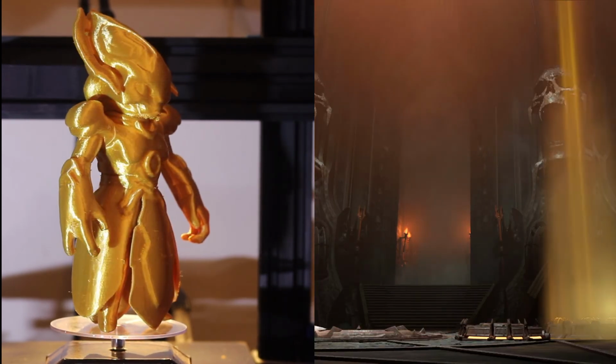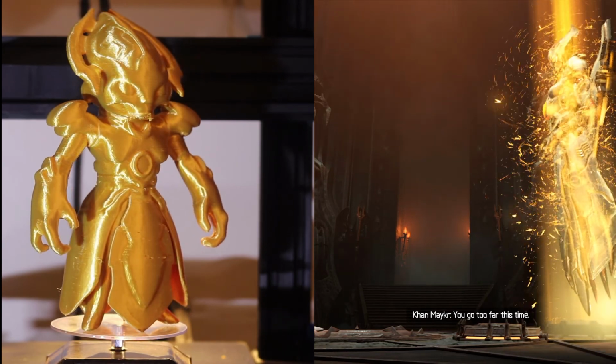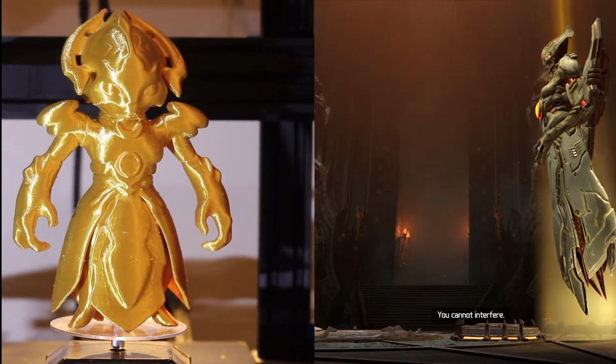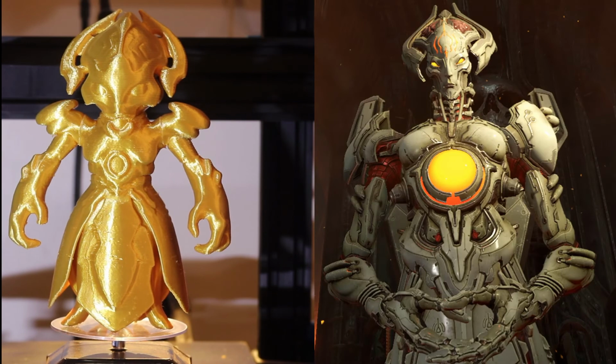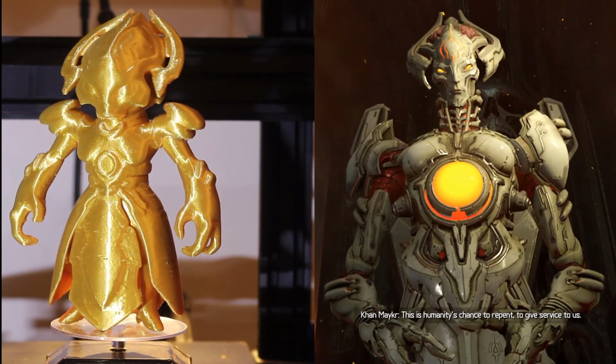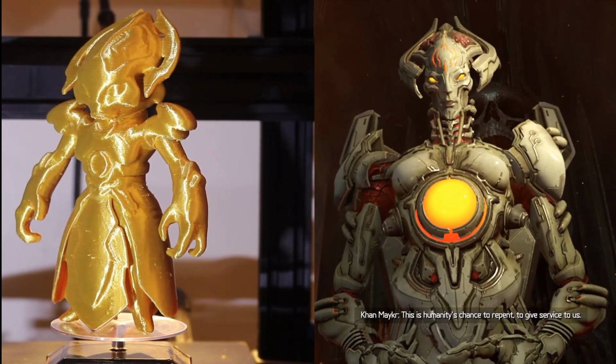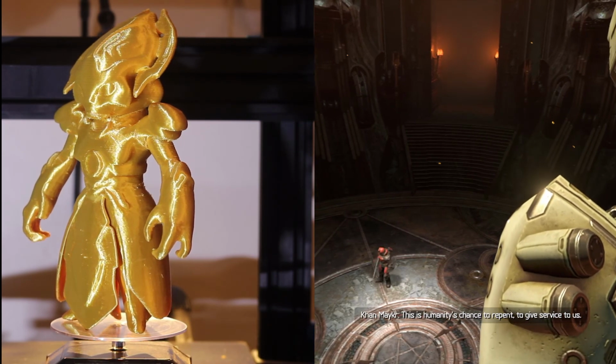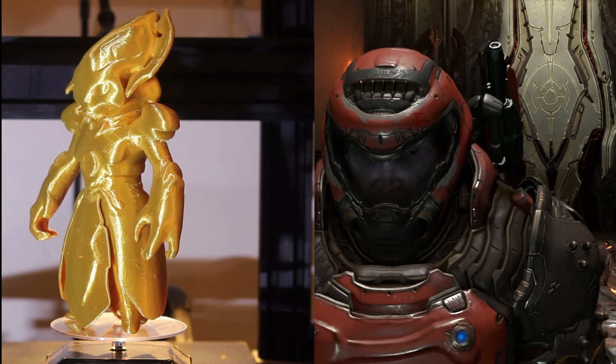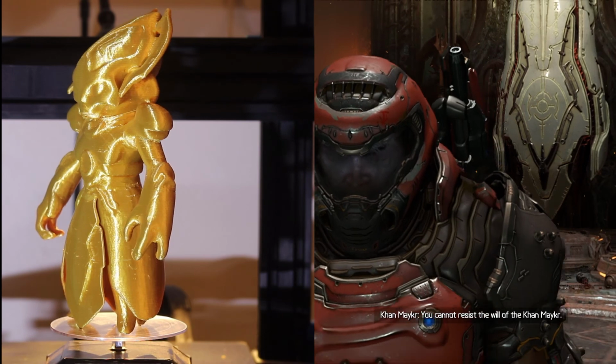This is not the first time I print with it, and it seems to have poor layer adhesion, and thickness is very uneven. I even had it stuck once in the filament runout sensor and mess up the print. Also, this is the first model, and you can probably spot defects on the back of the skirt because of the detached supports.